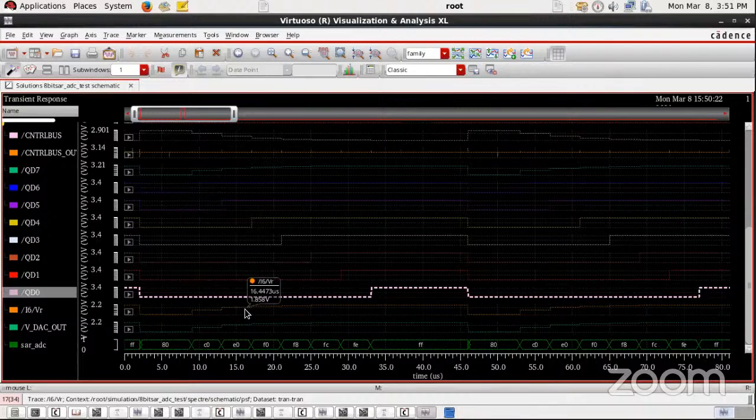Since we had weights of 1, 2, 4, 8, 16, and 32, we were able to get it. Suppose we are having 5 kg and 7 kg and 10 kg, and we are asked to check for the unknown weight. We will not be getting the exact weight, right? There will be some sort of quantization error. So that's it.